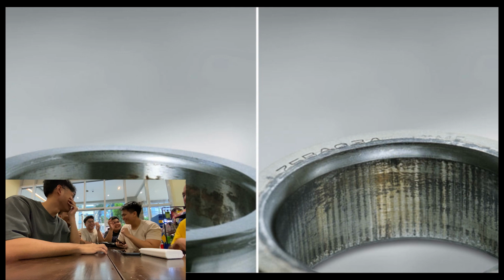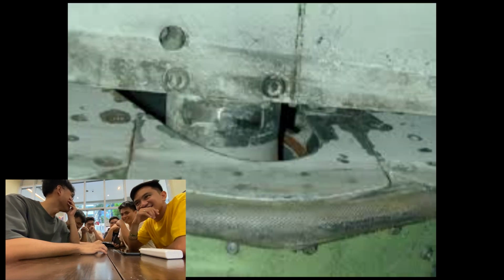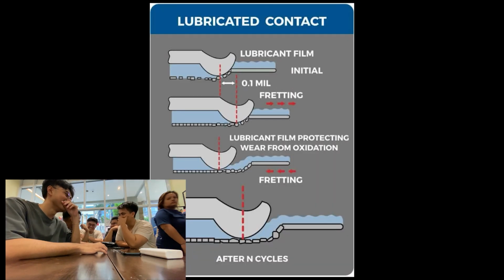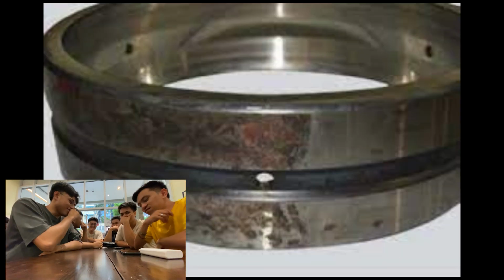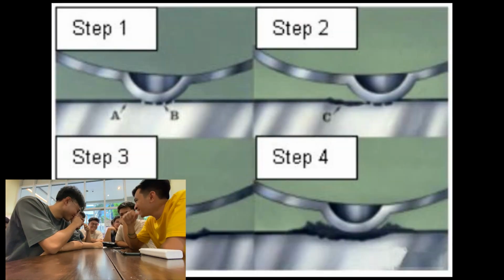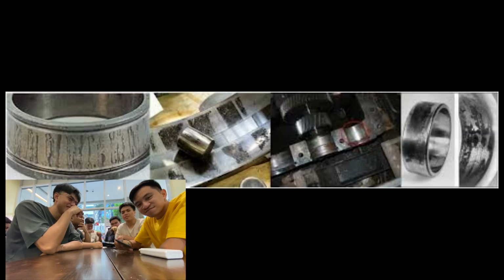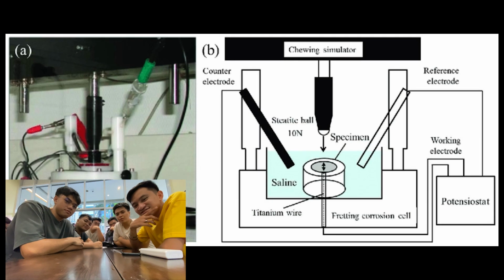5. Fretting corrosion. Fretting corrosion occurs at the contact areas between materials under load and subject to minute relative motion. Causes. This happens due to repeated cyclical rubbing between surfaces, leading to material wear and oxidation. Detection. Fretting corrosion is detected by examining the contact areas for pitting, discoloration, or material debris, often using magnification or surface analysis techniques.